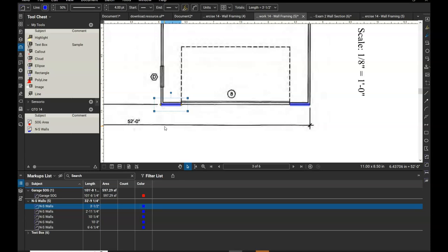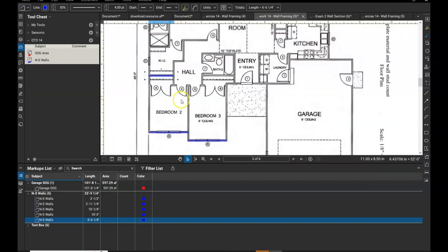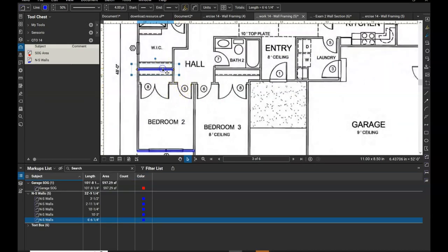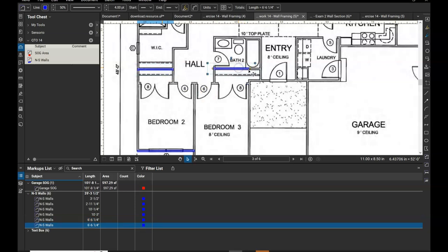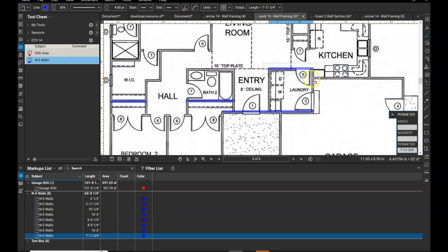Okay, I would open your property bar down below and then select both of them and rename it. Okay, and a way to quickly copy paste them too, if you select on one line, hold Control, click on that line, it allows you to copy too. So it's up to you, but once you start going, just keep drawing through all of your walls. Hit Control. This is very quick, but just kind of slow down to make sure you're seeing what you're measuring as you go.